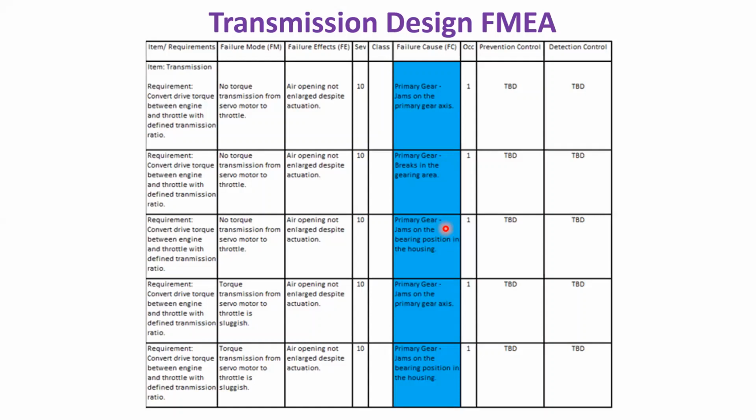Okay, again, it's not that this alone matters. AGMA is very much important because that is where you need to select what the face width should be, what the thickness should be, what the geometry of the gear should be. All this will contribute to the better performance of the gearbox.